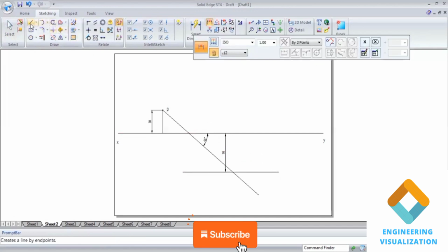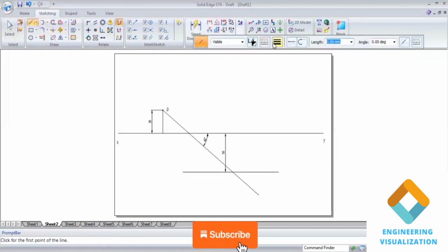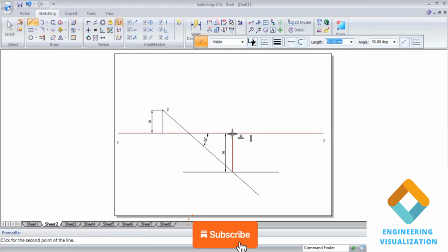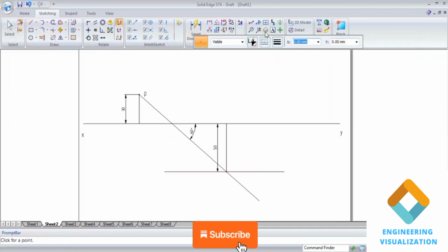At the intersection of this angle line and parallel line, we get exactly the other end point. Yes, here draw a straight line. Now mention the point here. Mention it is Q. This is the top view of Q.